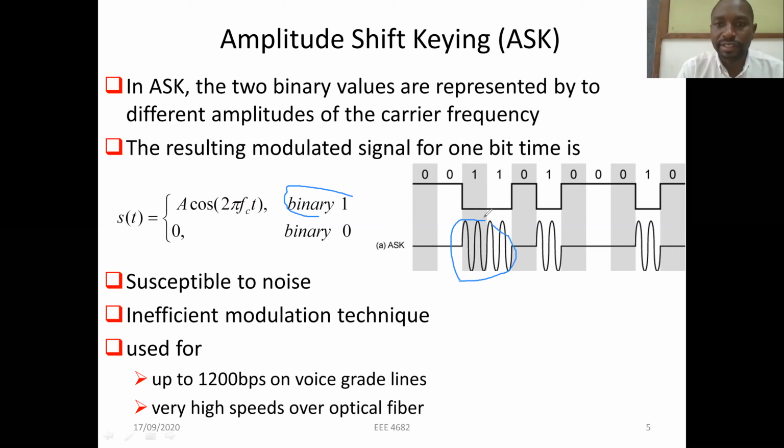The amplitude of the carrier here remains the same, while a binary 0, which is denoted in this format here, means that your amplitude will change wherever there's a 0. Equally here, the amplitude of the carrier signal will be changing, but wherever you have a 1, it means the amplitude of the carrier remains as produced from the carrier generator.